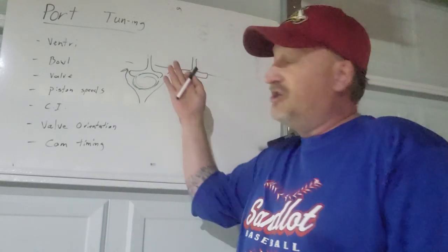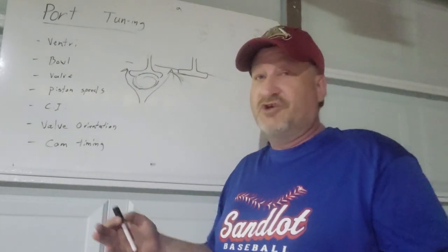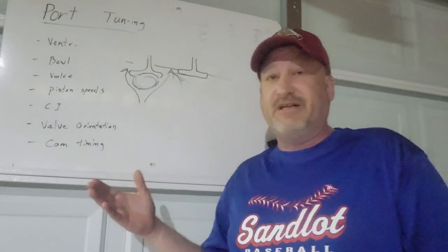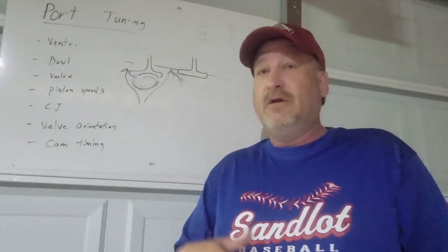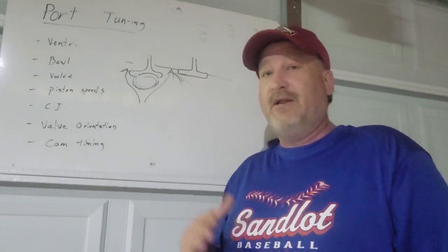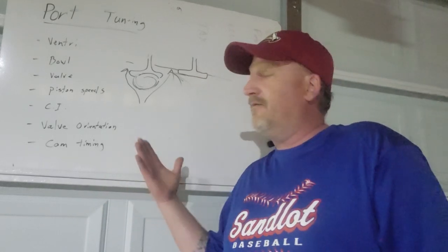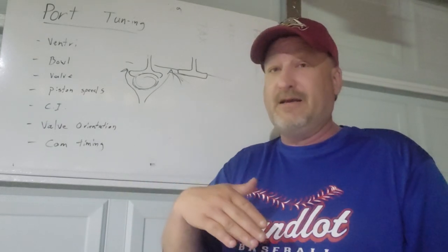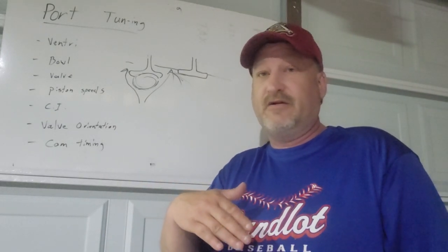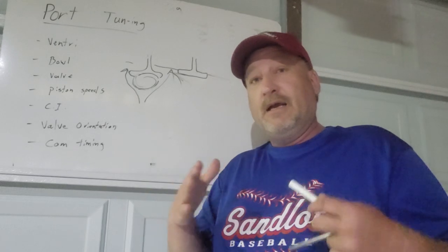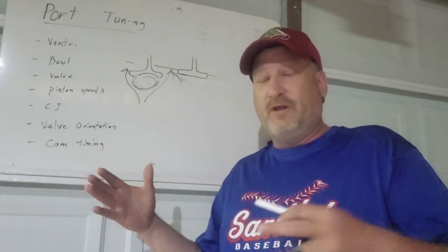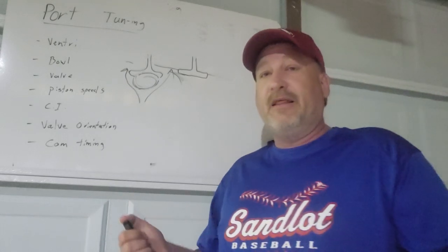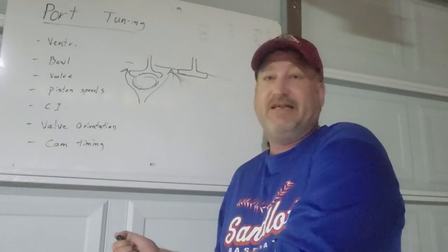Now, just like the intake port has reversion when the valve closes, there's also reversion in the exhaust system. So port tuning is when you're addressing the amount of reverse flow of the exhaust gases coming back into the exhaust port of the cylinder head itself. Mitigating when those two forces meet is dictated by the RPM range and the restrictions in the exhaust.